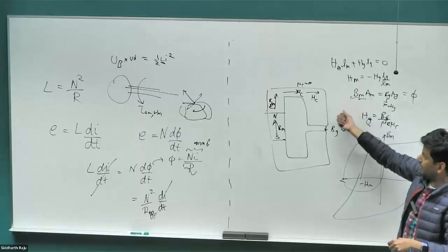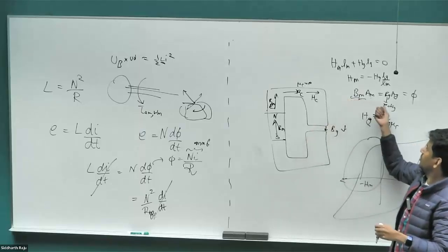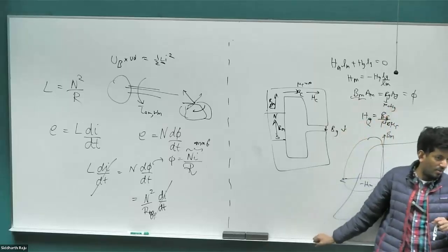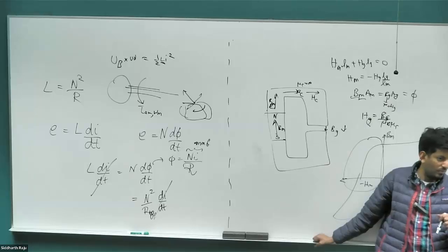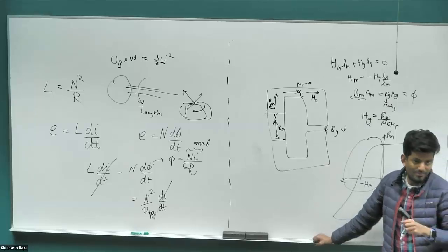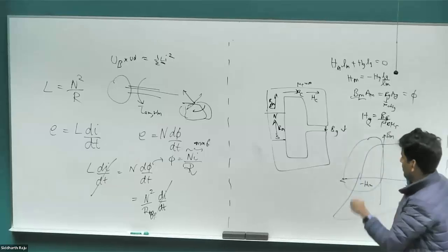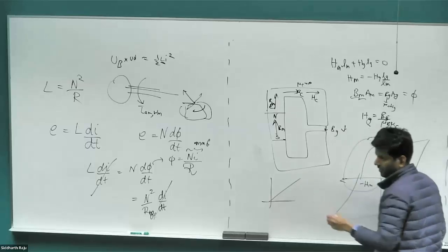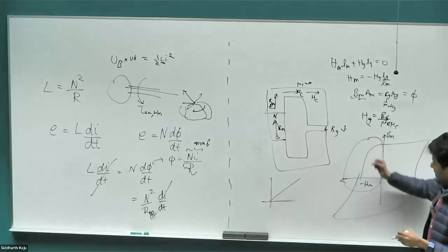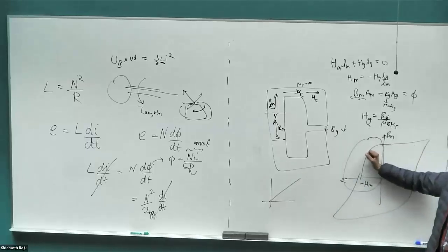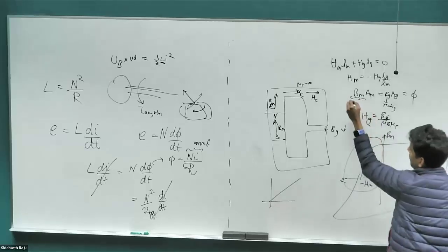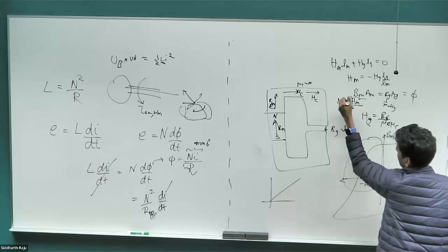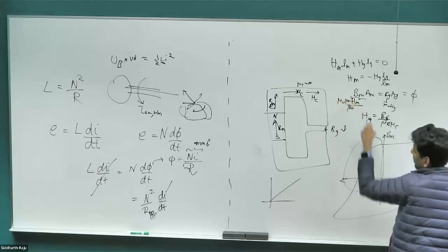When we solve our magnet circuit, can I replace BM as mu r mu naught HM? Thomas is saying yes. I think so, right? All right, no worries. We can't do that, because in the case of iron and air gap, we assume the B versus H relationship is linear. But here I have given you a graph which clearly shows it's a non-linear relationship. So you cannot just directly say BM is HM times mu naught mu r, because mu r is not a fixed value, it changes.